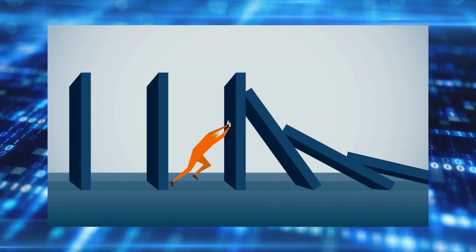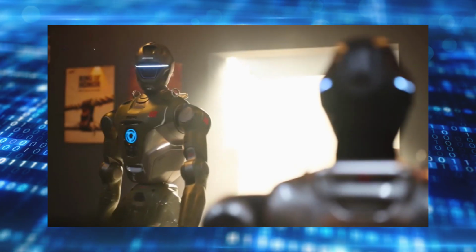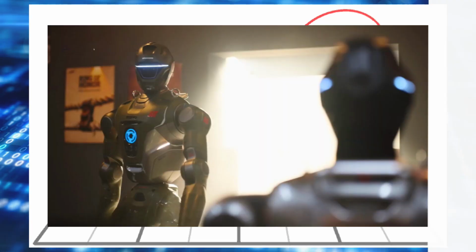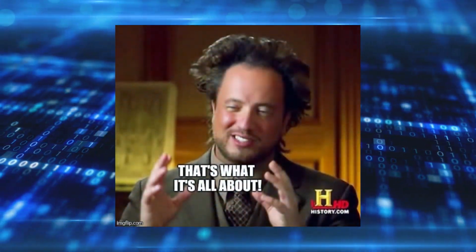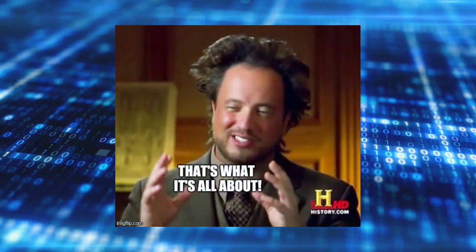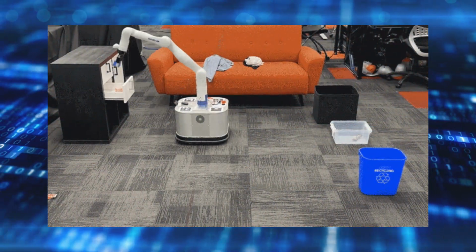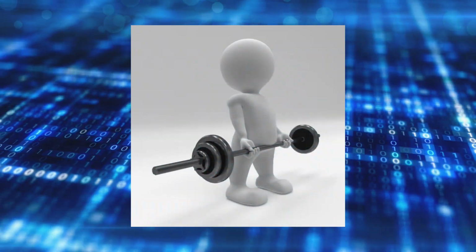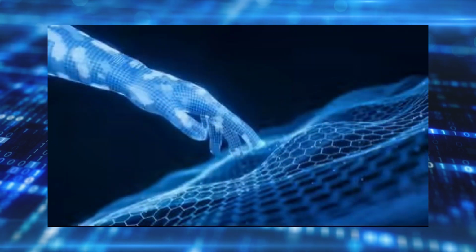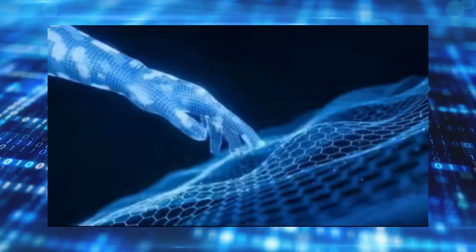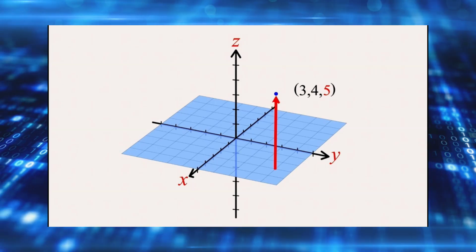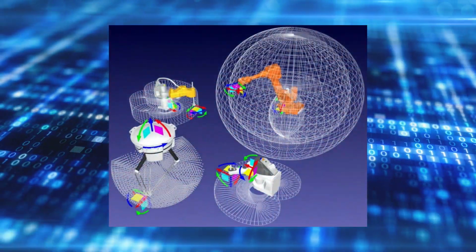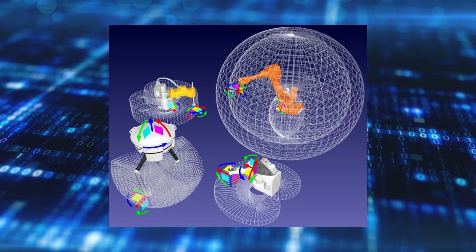Inverse kinematics is a much more challenging problem. As this topic applies to humanoid robots, defining the position of the hand in 3D space relative to the shoulder is what inverse kinematics is all about. Anytime the robot picks up an object, this is an exercise in inverse kinematics. Basically, if I want my hand to move to a specific location, inverse kinematics will calculate the angles all of the joints in my arm need to make in order to reach that position, given of course that the point in question is actually within my reach.